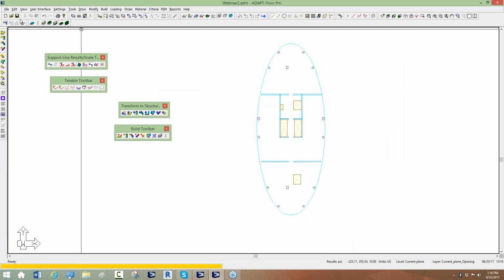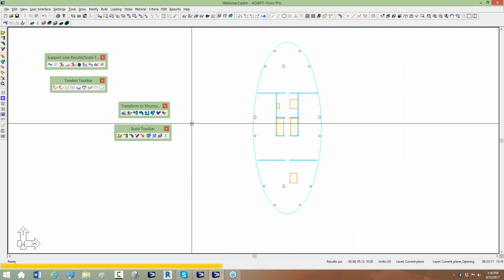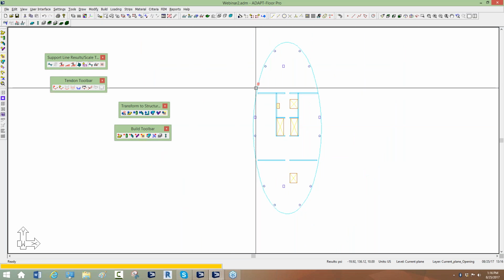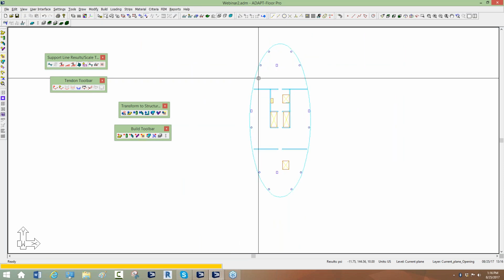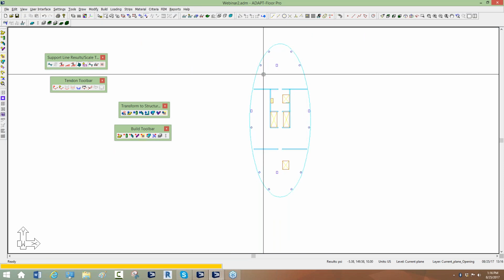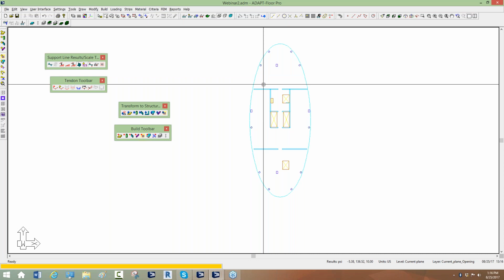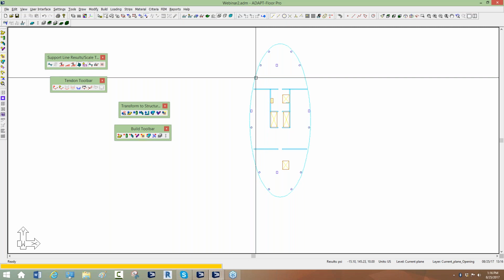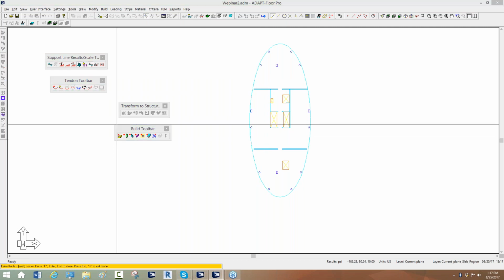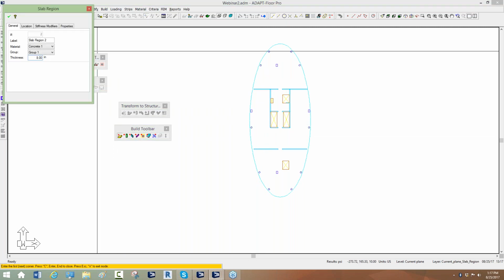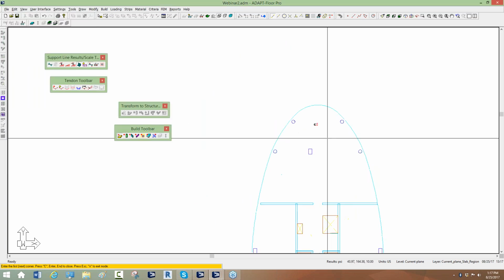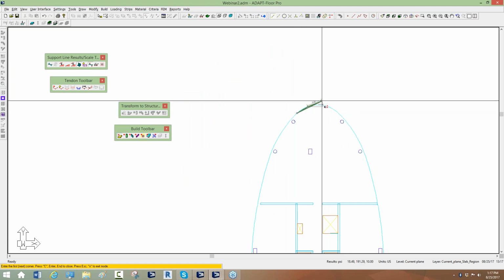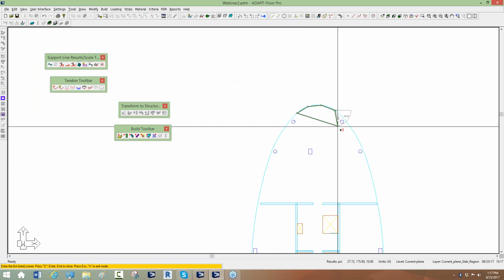And then finally we'll go ahead and model the slab. Now the slab in this case is represented by tiny little segmented lines. The program cannot model, or cannot convert, a circle or an arc or an oval shape that's continuous, so you have to segment the slab. So I'll go ahead and set my slab depth to 8 inches, that's the default, and I'm going to segment this. So it's going to be slightly rough in terms of its shape, but it'll be good enough for what we're trying to accomplish.